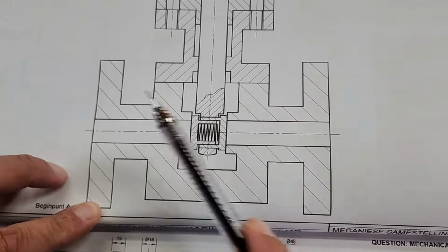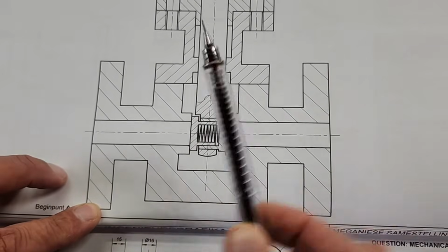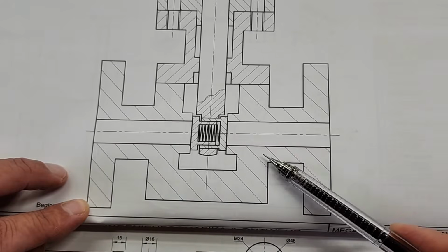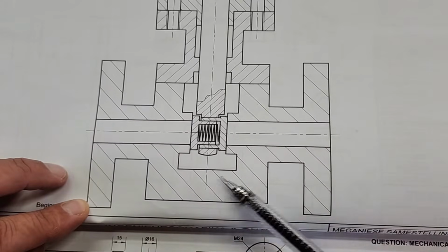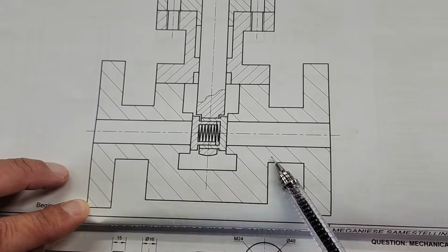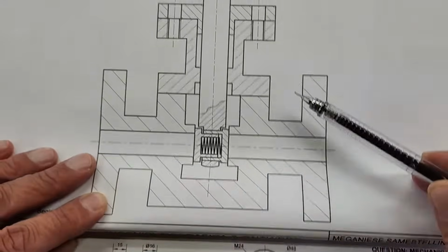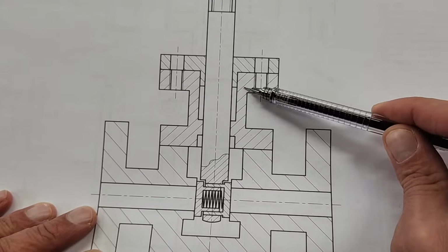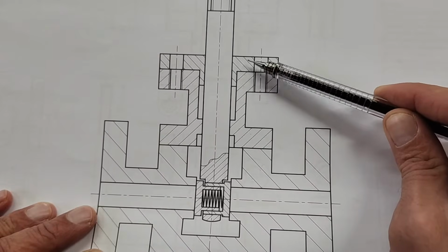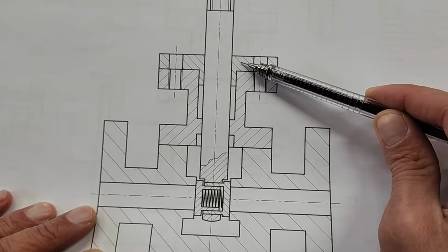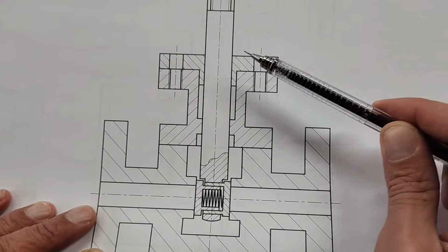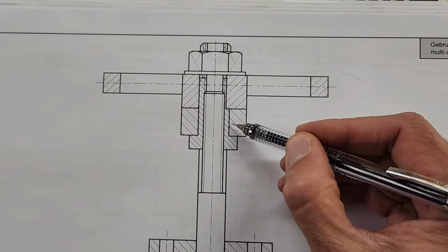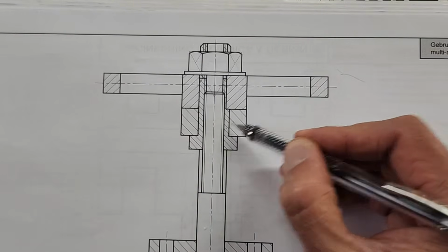All right, and which will differ at 45 degrees in one direction or 45 degrees in the opposite direction, and the spacing is the other part. What we do want is a consistent hatching pattern all the way through the same component. So you can see here the bigger holder, the smaller components, as they change, the direction changes, and so 2 adjacent parts will always have different hatching, either direction, or if it gets too complicated like here, you can see the closeness of the 2 are different.